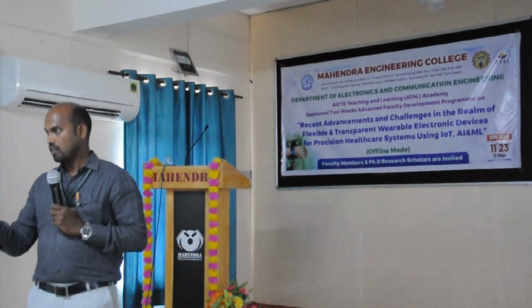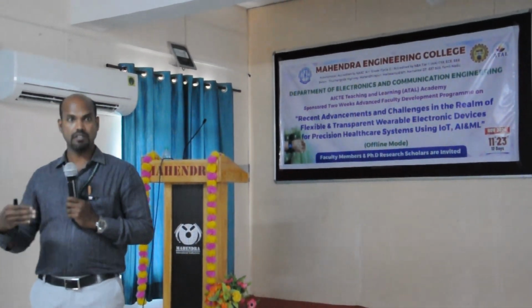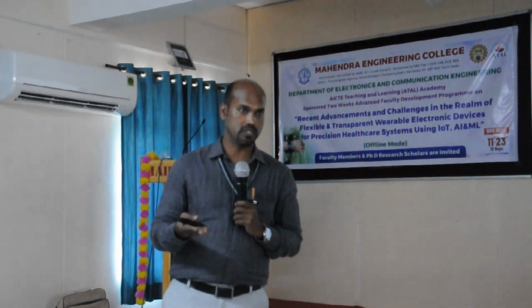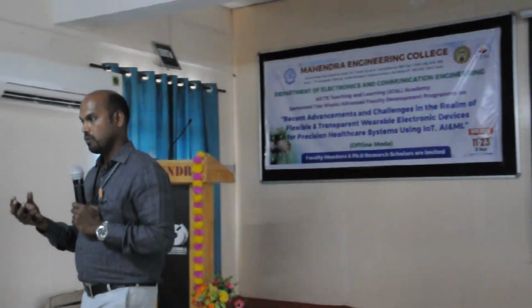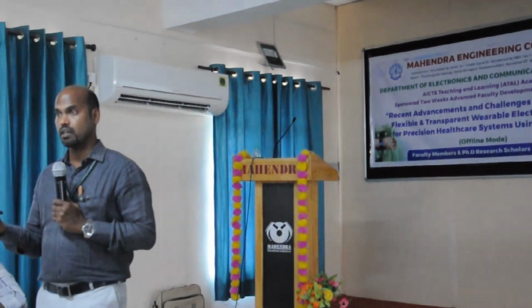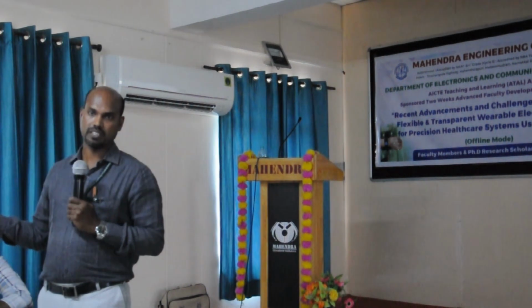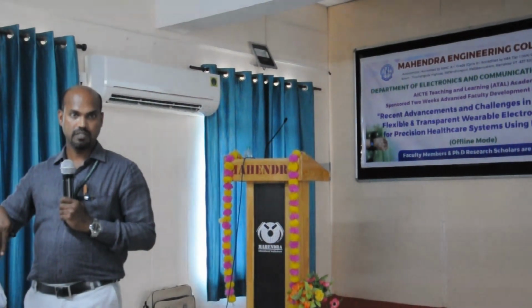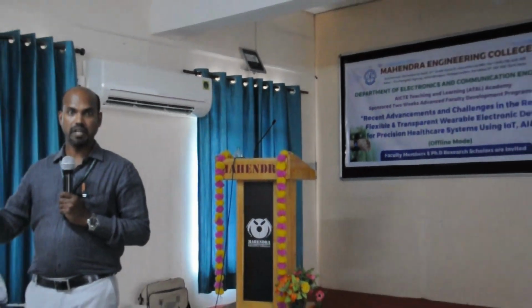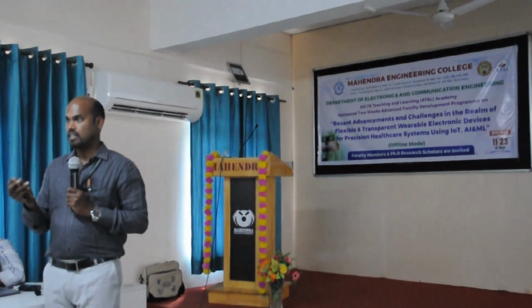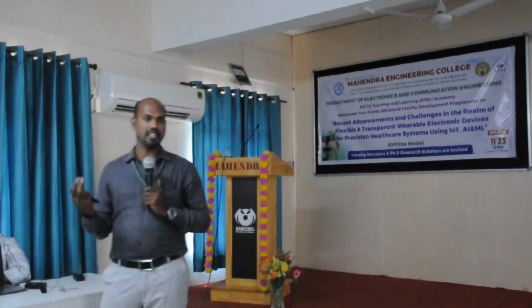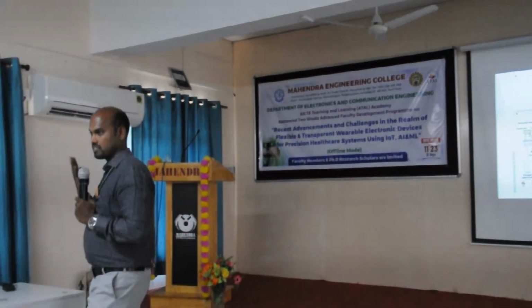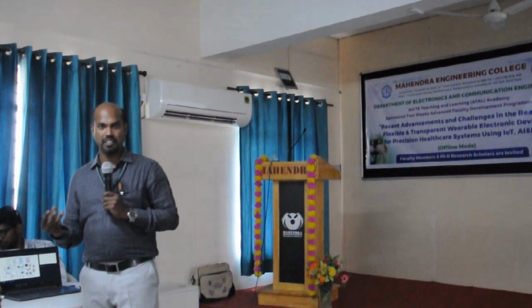From whole blood, glucose is detected with enzymes modified on the electrode, which is called glucose oxidase. That will convert the glucose into gluconic acid and hydrogen peroxide. The byproduct hydrogen peroxide will be reduced at the electrode, generating a current. In a few seconds we see a number like 120 milligram per deciliter, or 200, 160, 80 or 70 in the glucometer.